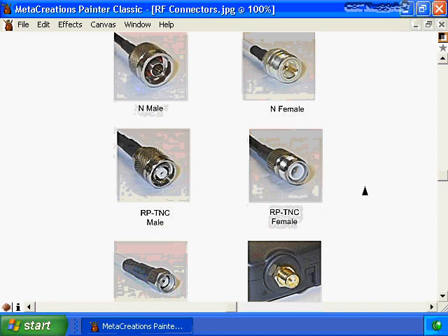And if you think about it, there's a lot of wireless equipment that's being installed now in the home environment and the small office, home office environment by non-professionals. So you'll find with these types of equipment, they'll use RP connectors in an effort to help prevent home users or non-professional users from mixing and matching different equipment, and as a result creating a non-FCC certified system. And that's why a lot of companies that are setting up wireless LAN will purchase their antennas, their cabling, their connectors, their wireless LAN infrastructure devices from a single vendor, so everything fits together and complies with the FCC rules.